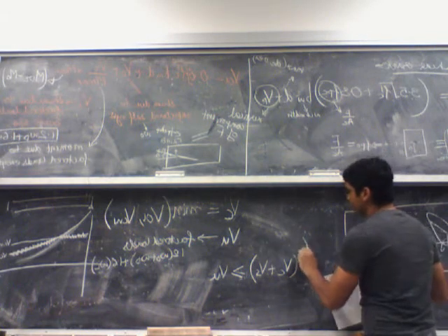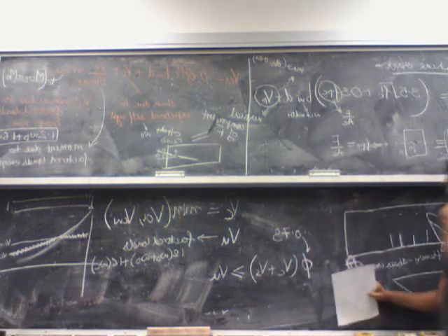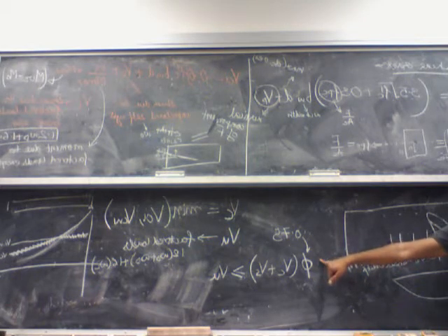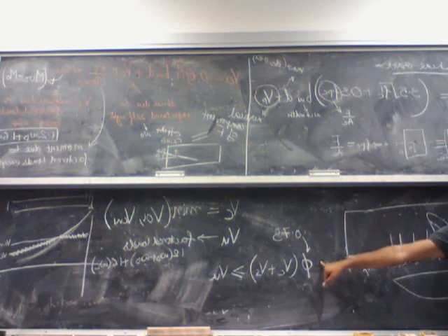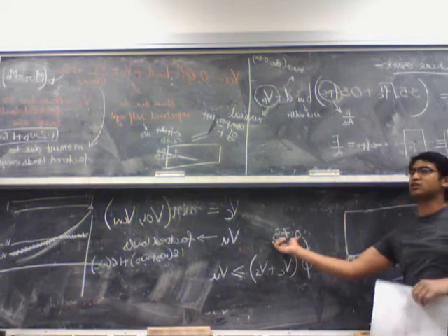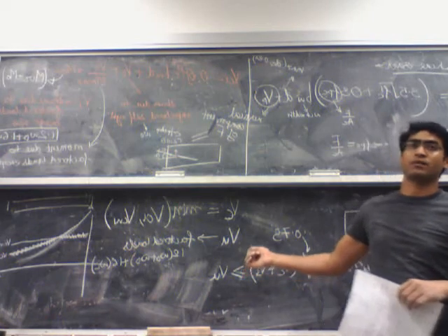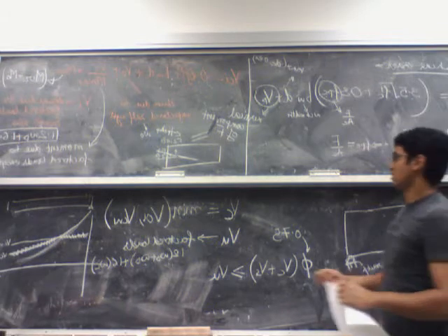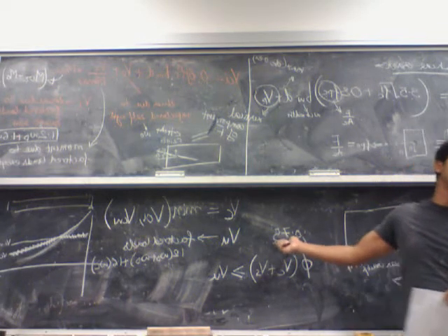For shear design, this phi is always 0.75. What is the reason this phi is less than the phi that we generally use in the moment check? The thing is, if a beam fails in shear, it is going to be a brittle failure. It will happen suddenly, which you don't want. So you reduce the capacity of the beam by a greater amount to make sure that brittle failure doesn't happen. In case of a flexure failure, it's a ductile failure. So even before the beam fails, you will see a lot of deformation in the beam. That's why we have a smaller strength reduction factor for the shear capacity.